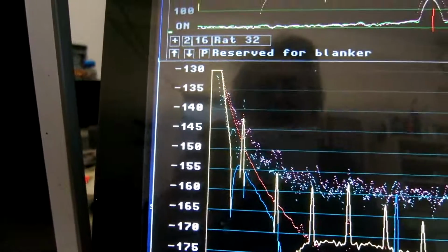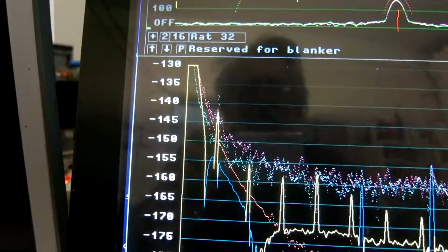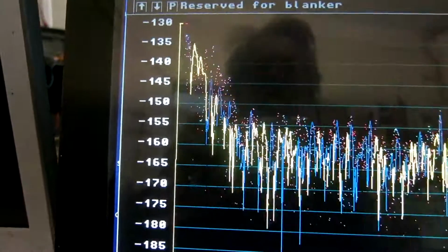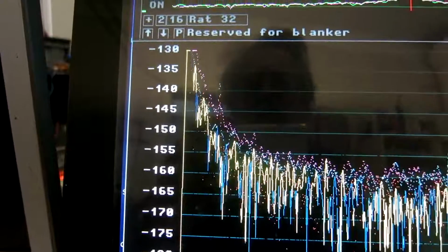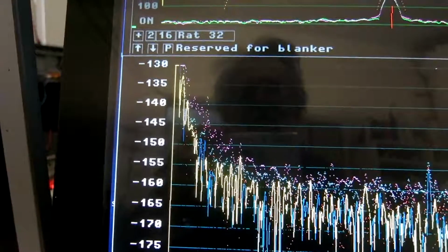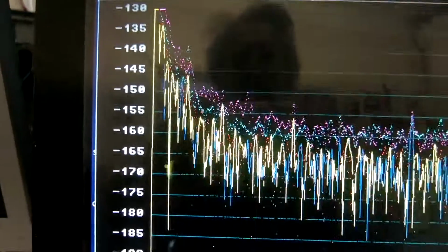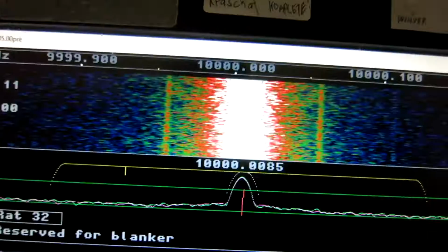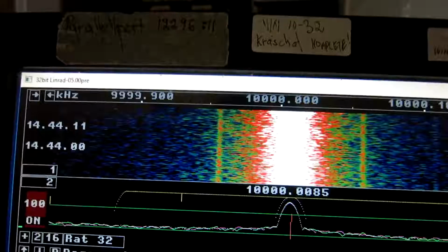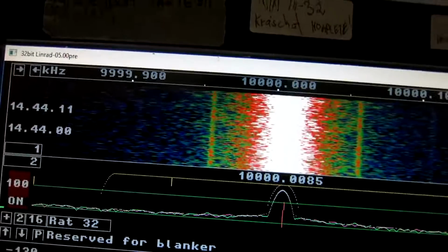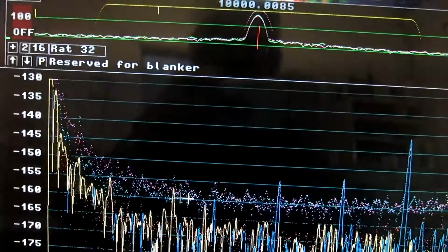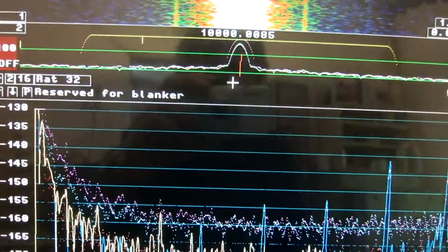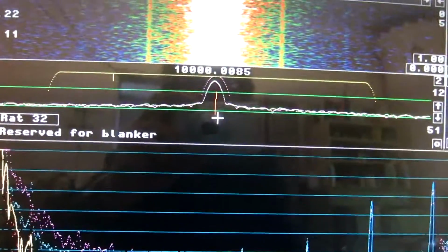And you can see that here, this average jumped down. And if I clear the screen, like this, we can see pretty rapidly that things are again as they were before I made this change on the time constant. The phase detectors used to produce this FM demodulated signal, which you see the spectrum of in this analyzer window. That FM detector is an IQ demodulator.